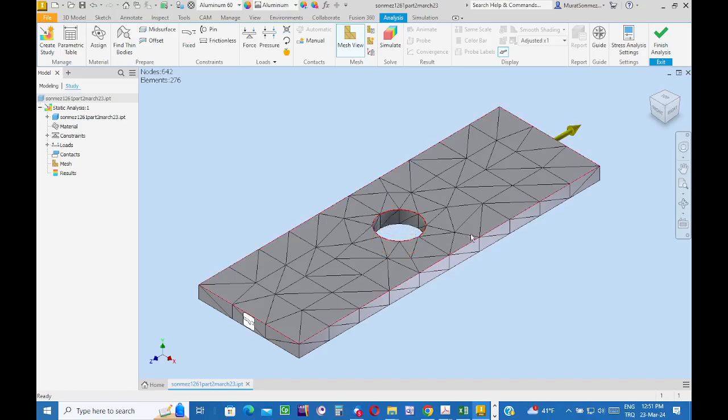Since the maximum stress is important and the maximum value is to be calculated more accurately, instead of using such a coarse mesh, use a finer mesh. But in doing this, I'm going to enable the software to set the mesh size in the background. Step by step, decrease the size of the mesh in the vicinity of